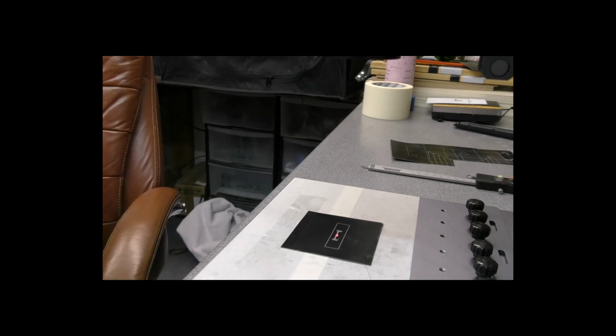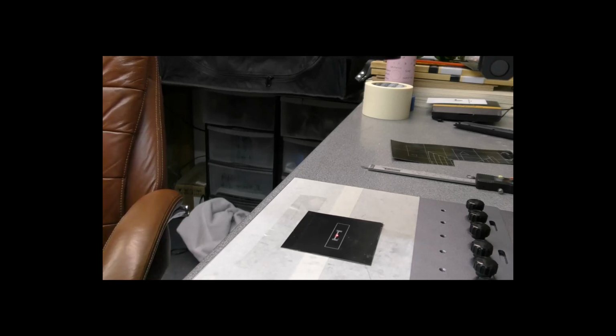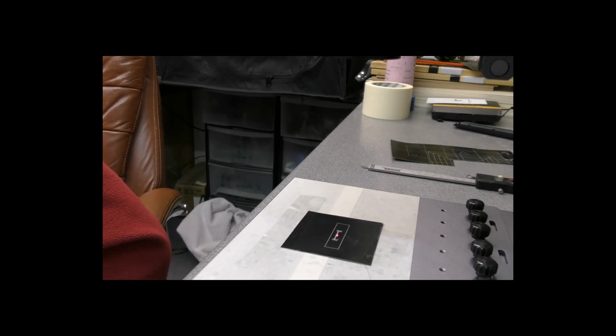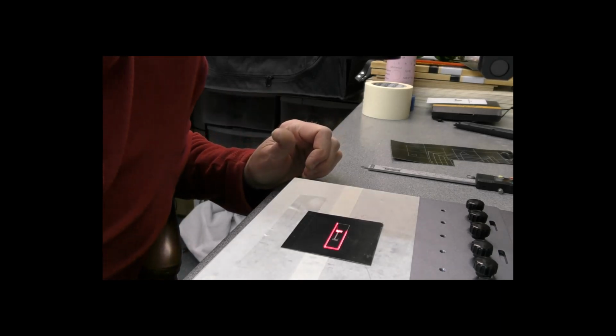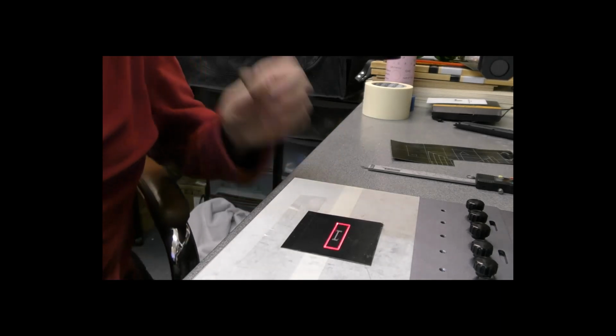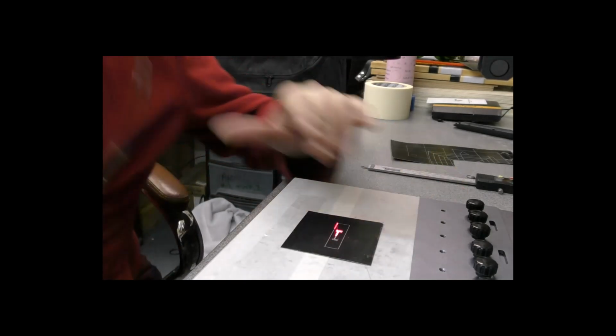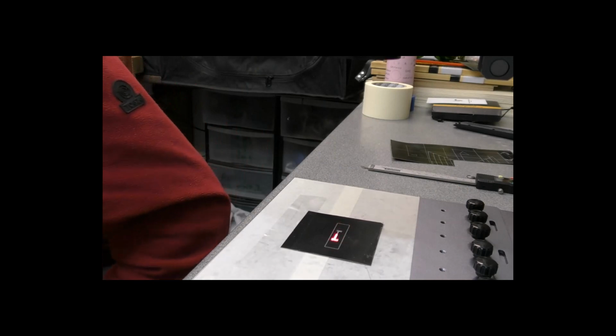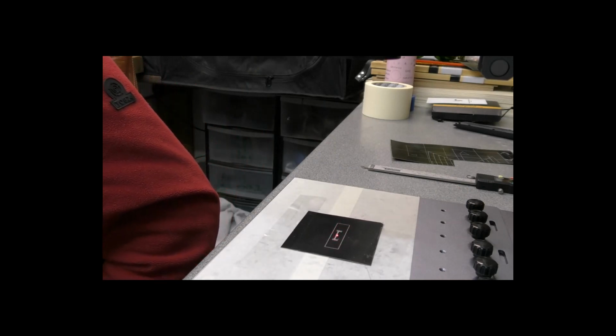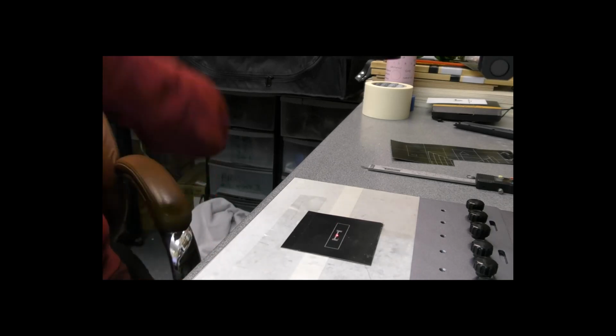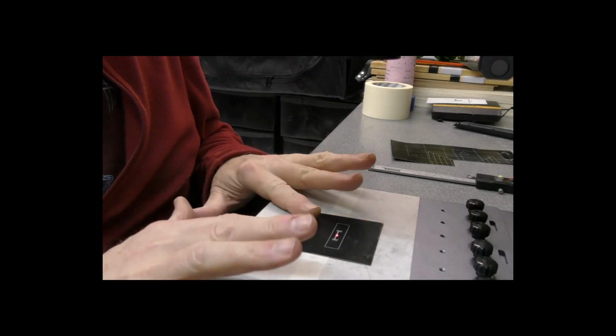So we can go back to F3 and we can just change that size ratio from what I had it on back to 1.0110. And if we do a preview now, yep, that is smack bang over the top of the lasered image. So yeah, okay, well that's perfect. This is clearly very well set up. No change is required there, but that's actually what it does.